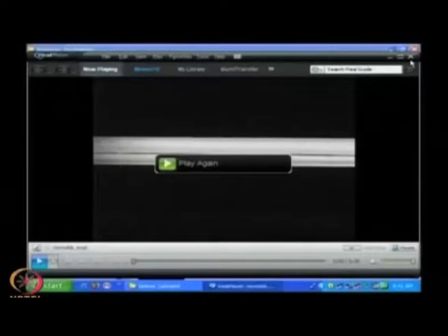Here it is a regular orderly motion. Now you see that the regular orderly motion is disturbed somewhat. When it is disturbed, the dye streak is no more straight and parallel to the axis of the tube, but it is getting diffused, and at the end you see that this is a totally random and chaotic motion, and there is a whole lot of mixing within the flow. So, something is happening which is changing the regular orderly motion into some random or apparently erratic motion.